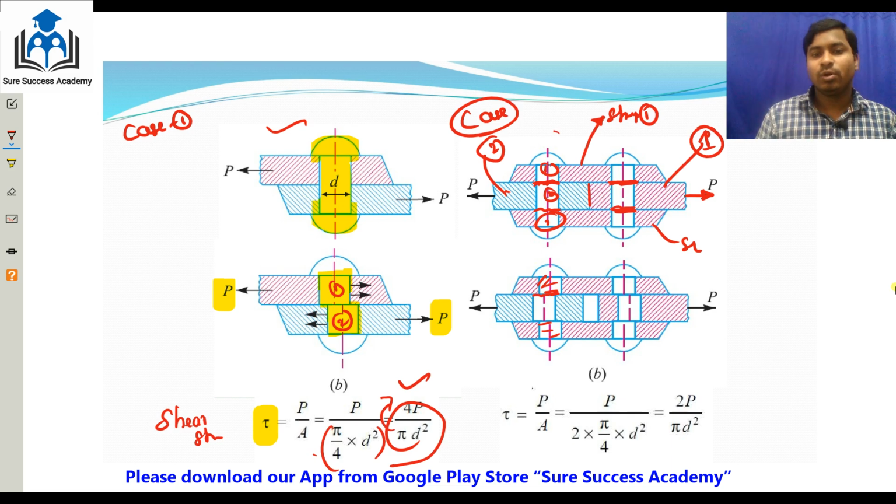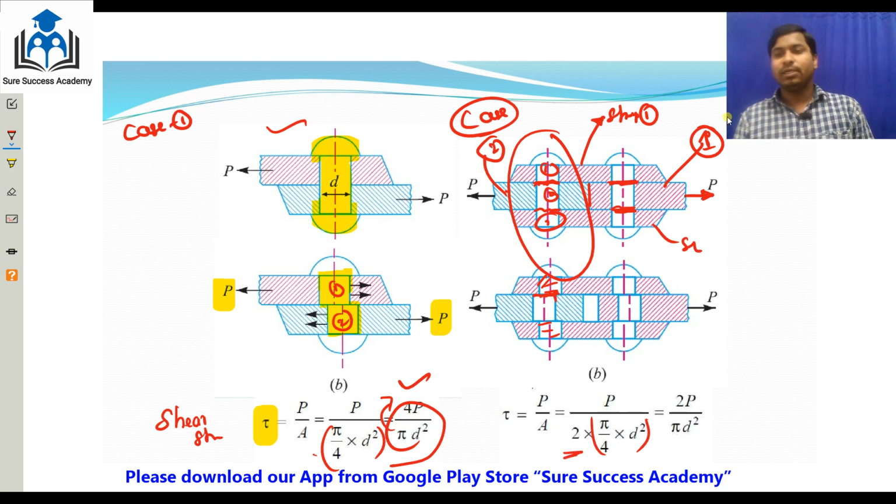If we consider only one part, P by A is equal to π/4 d². This is one resisting area. Then this is two resisting areas, double shear, so it is two times π/4. In machine design, you have to see only the resisting area: how many resisting areas, and which are they.